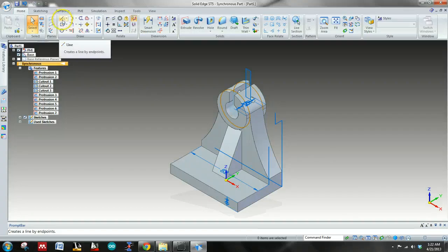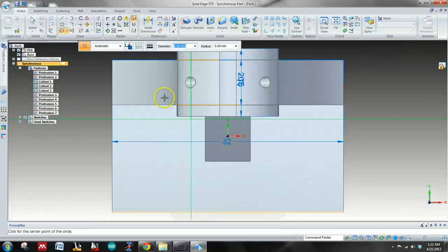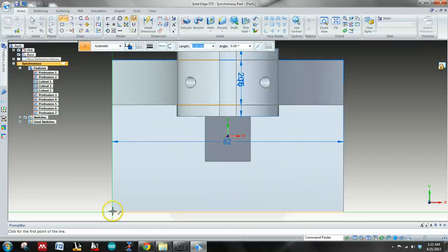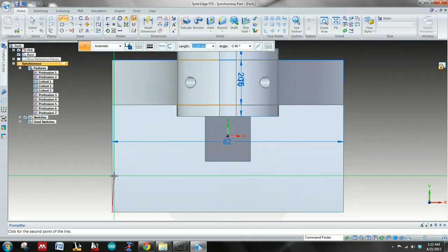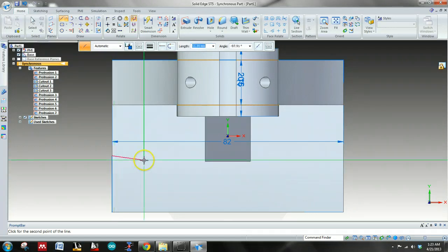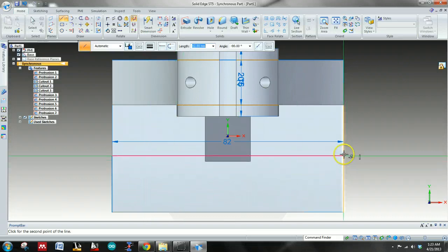And then to do that, we'll come up here to the circle, come over here, hit F3, Control T to get you to the top. And I'm sorry, instead of putting in, we don't want to put the holes just yet. We actually want to mark them out. So to do that, we'll go back to our align function, hit this. They are 20 up, tab 0, enter. We'll run that all the way across there, so 82, tab negative 90.